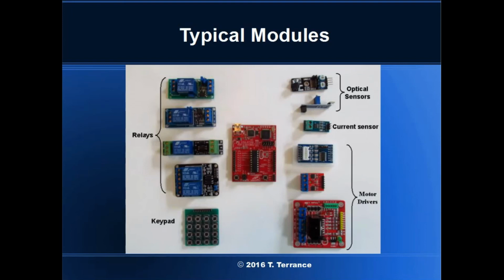Upper right are optical sensors. These are generally infrared devices and, generally, use a 38 kHz modulation on the signal to prevent jamming by infrared light sources like the sun and incandescent lights. But this feature is not universal, as I found out to my chagrin one day. By the way, if you want to see whether the light is on, your cell phone camera can see infrared light, use it as a detector. When the optical detector trips, the signal line goes to ground.